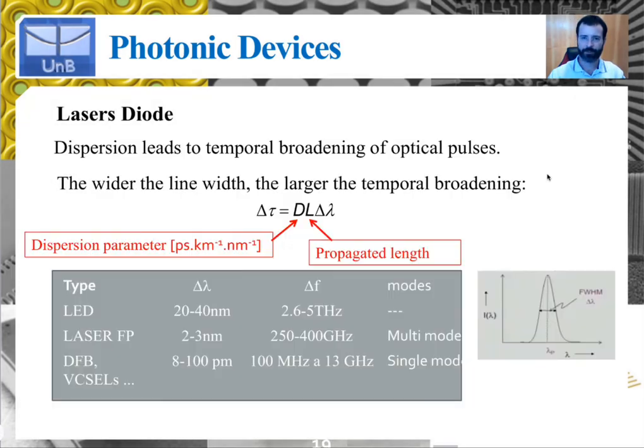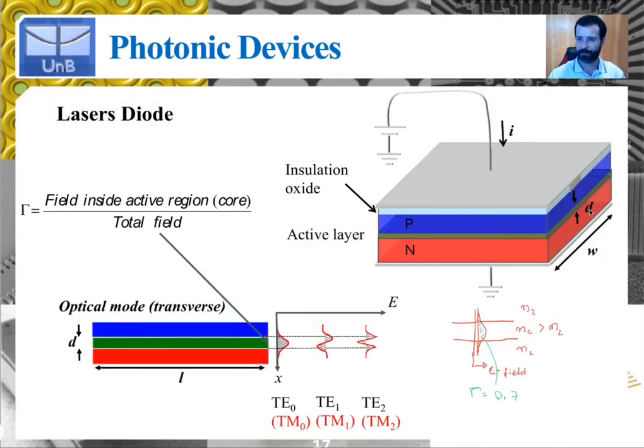If we consider the light actually coming out of the output of the waveguide, the mode, this would correspond to this dimension right here, because of lateral confinement, which can be achieved, as we've discussed, by gain guiding or index guiding. The typical width of the waveguide is going to be around 8 to 10 micrometers. So this is the lateral dimension, that's why the 8 micrometers.